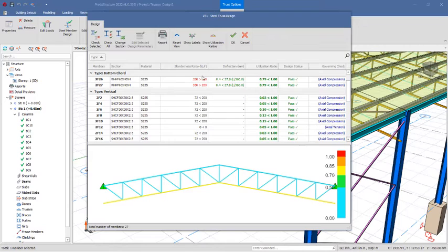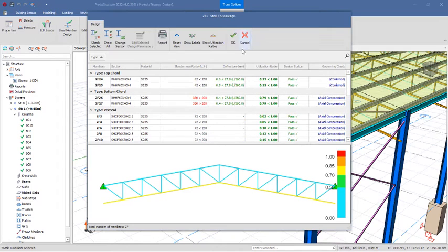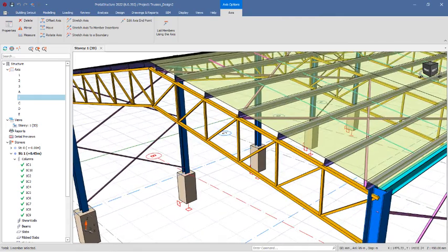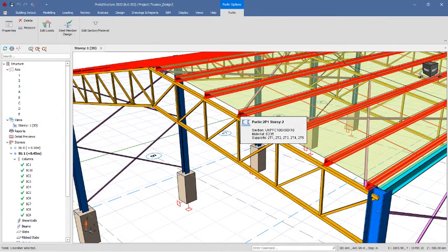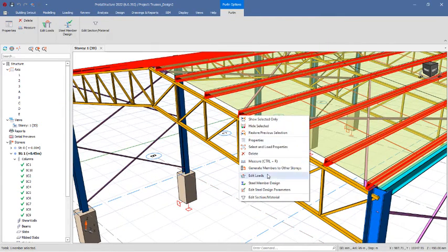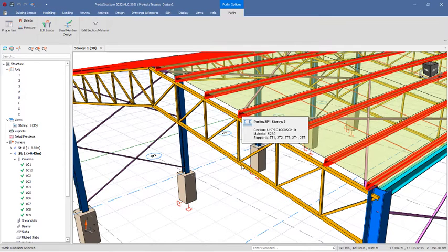So for you to be able to overcome this slenderness ratio, what you can do is increase the thickness of the sections, okay? Or you make the section less slender, like you make it shorter. I believe that this can also be corrected on site during fabrication, okay? So the steel trusses are quite okay. Click on the OK option. So over here, let's check the pole lines. Select that, right click, and then click on the steel member design right there.